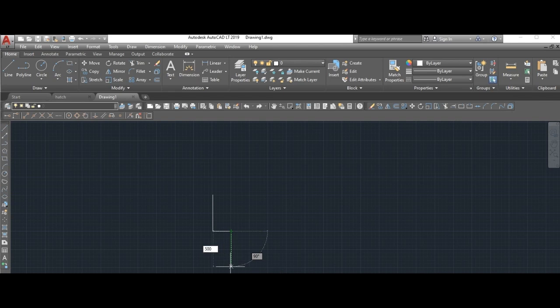I press enter. So the direction you position the mouse pointer, it follows you there. So I put this one here, I type 250. I press enter. Then I take a long one here. Since the other two directions was 500, I can decide to make this 1000. I press enter and I press enter again. So I already have something beautiful here.